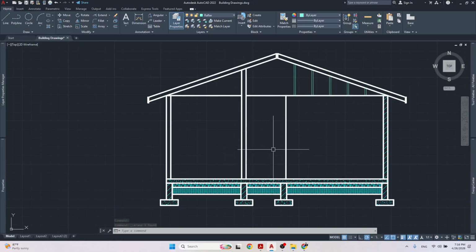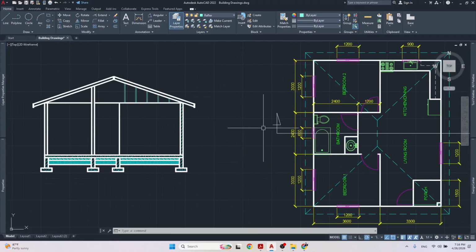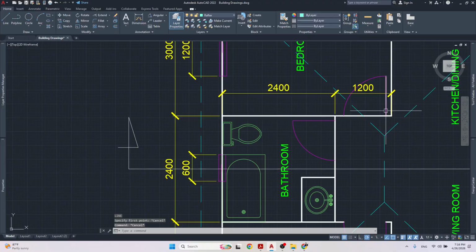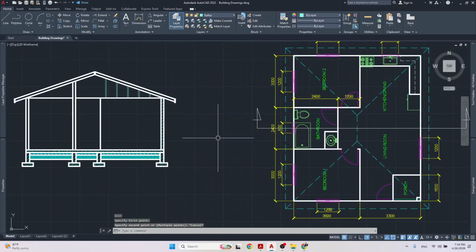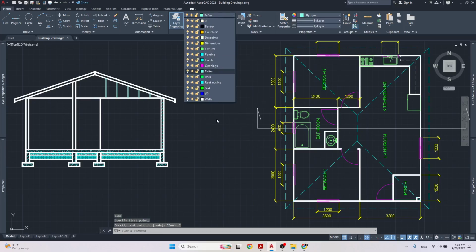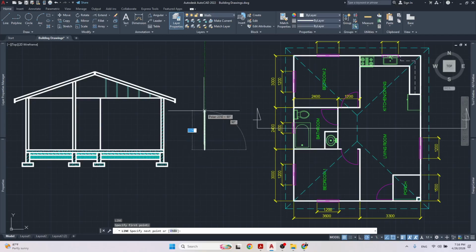There's supposed to be a door in here, so they would give you the specifications for the door. Let's say the door height is 2000 millimeters and the width is 750 or 900, whatever it is. I don't know what this is. Let me measure this. I'm going to just use the width. So 900, and the height of the door would be say 2000 millimeters, right, which is almost 7 feet. So I'm going to draw a frame for that door. Let's say, go back to my wall layer. So 900 across, right? 2000 come back down, and then I'll just close it off at the bottom.